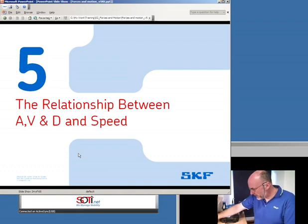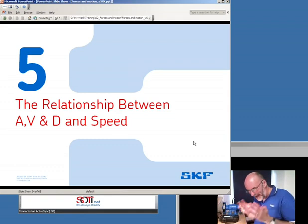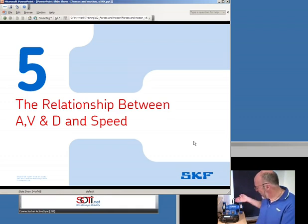Well, the get out of jail free card, for those of you who play Monopoly, is the standard will usually tell you what to measure. ISO 10816, Part 3, which is for general industrial machinery, will tell you to measure vibration velocity from 10 Hertz to 1,000 Hertz, and also to measure vibration displacement.